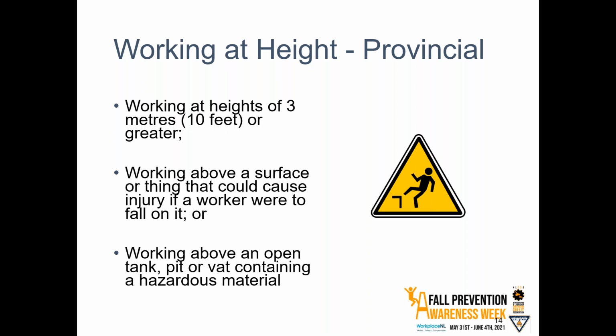But again, I just want to highlight that working at height, yes, in the province, we do define that as 3 meters or 10 feet. But again, there's more to it than that. It could be less if, again, there is something that you could fall onto or into that could harm a worker.